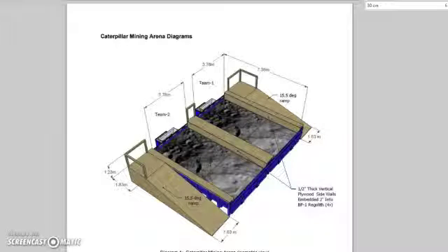So now, an environment can be created similar to how you create a robot, though environment items are usually simpler because they don't have to perform tasks, so the primary focus is going to be geometry and texturing. Either description format can be used, although SDF might be advantageous in some scenarios because it offers more features such as lighting. In the beginning of creating an environment, consider what important elements are essential for the simulation and how a simulation can encompass these within its constraints.